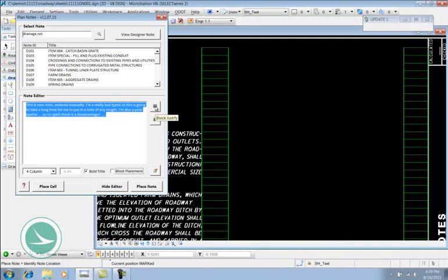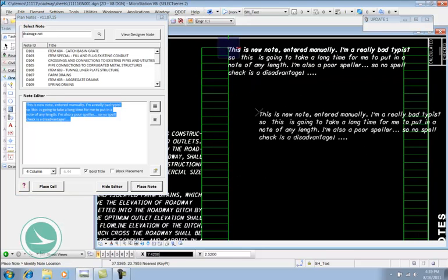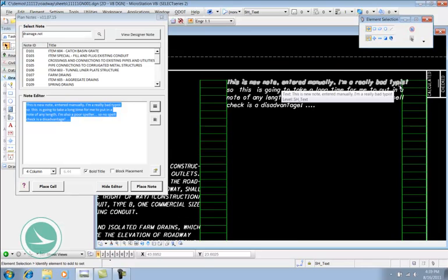What the block justify does is look at my line length and attempt to fit the proper number of characters within that line width or column width in order to end up with a block justification. Now, it's not going to be a true block justification because I'm using my active font and I'm not using a monospace font. So in other words, not every character occupies the same width. But if I use block justification, it'll pad some things with some spaces, and you'll see maybe some extra spaces put in here to attempt to make these roughly the same length. So right there you can see there's a couple of places where it's added an extra space between some of the text.